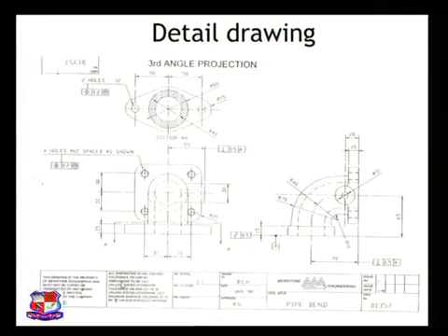For example, all dimensions are in millimeter, tolerances on linear dimensions to be this one unless stated otherwise, tolerances on ES or AS. These tolerances are used in this drawing, and here the drawing number is written in reverse order. You can see here in reverse, because if you fold this sheet in such a way that this will come in forward direction, and on the first page we can see this in an appropriate place. So this is provided to have proper folding of the drawing.